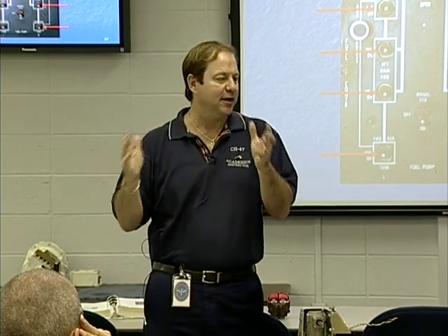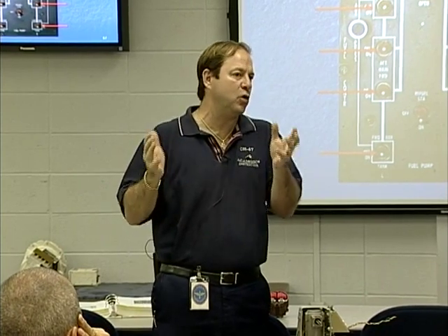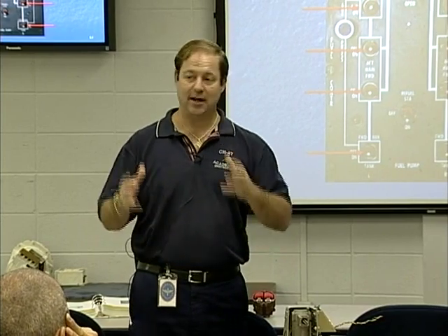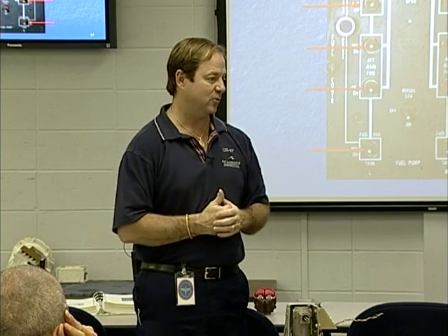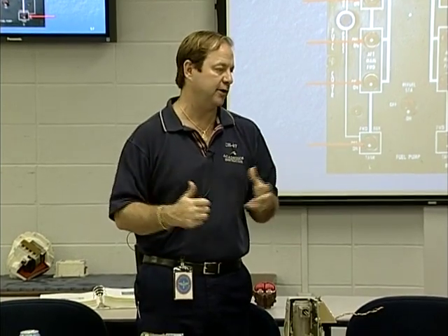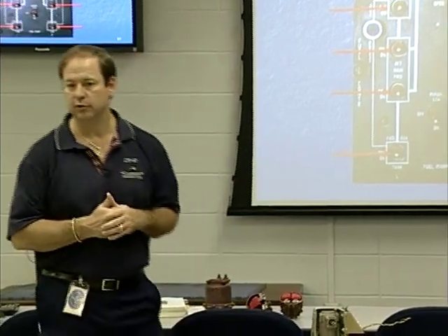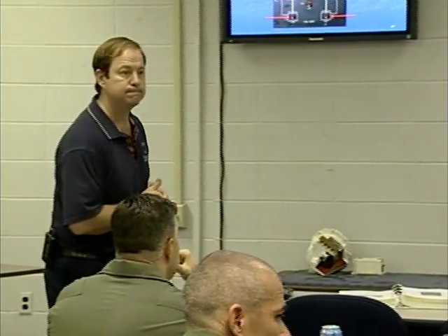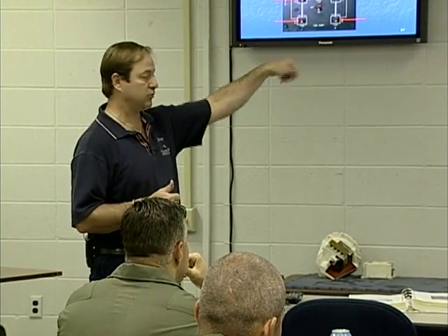Keeping in mind that the internal tanks are still pumping into which tanks? Into the mains. And that main tank fuel is going up to the engines or the heater or the APU, depending on what we're talking about. But reality is, by this time we're flying, so our main concern is our engines. So that would be the only time that I'd have to turn them off. So you never tend to make switches off? You just turn off the aux fuel pumps. You have to leave the mains on, but reality is the same things are applicable.